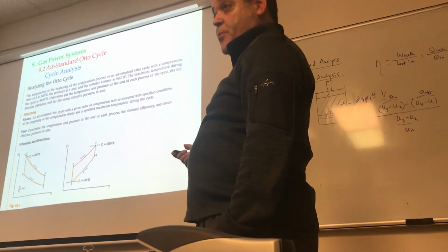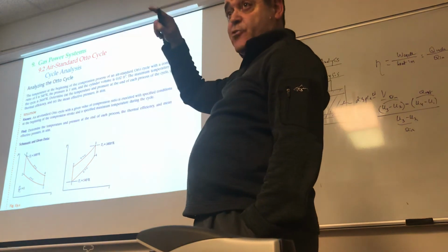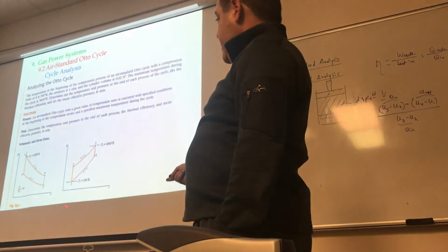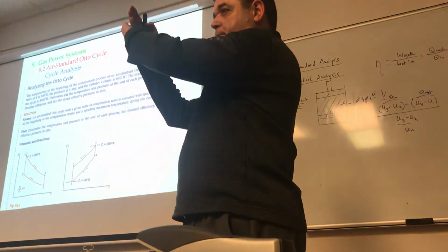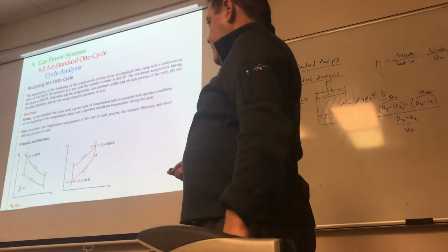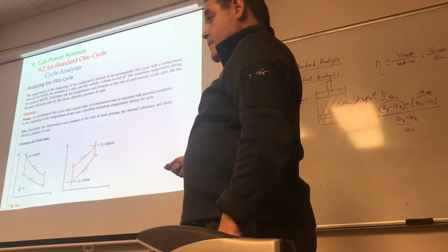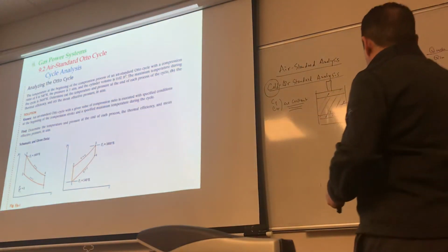As opposed to the vapor power cycle, in which we talk about state 1 as being the entrance to the turbine, here state 1 is the beginning when the piston is down and you are compressing the air, right? And then 2 at the top dead center, then heat addition, right? Power cycle, and then heat rejection. So essentially, 4 different states.